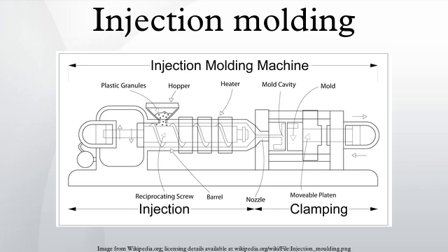Shrinkage must also be taken into account when determining the draft required. If the skin is too thin, then the molded part will tend to shrink onto the cores that form while cooling and cling to those cores, or the part may warp, twist, blister or crack when the cavity is pulled away. A mold is usually designed so that the molded part reliably remains on the ejector side of the mold when it opens, and draws the runner and the sprue out of the side along with the parts. The part then falls freely when ejected from the side.